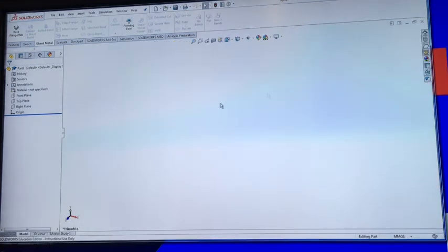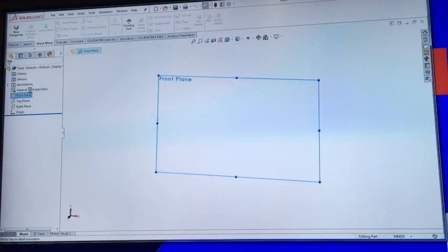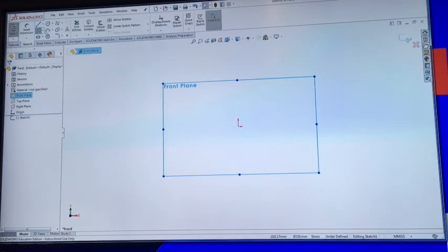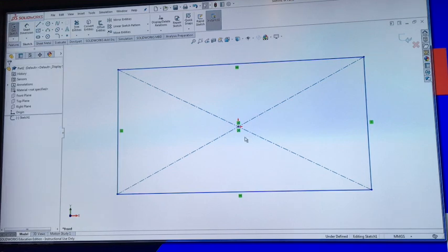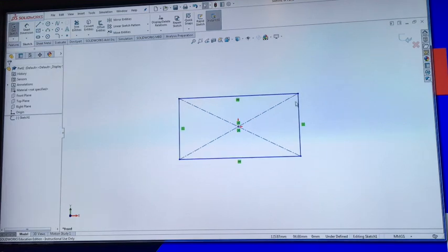The basics of how it works, there's 2 options. You either build from scratch using the metal tools, or you build like we did with the form bracket using the basic extrudes and cuts and then convert it later. To start with from scratch, your base flange can be any shape, but to do flanges or bends off it, you need flat edges.